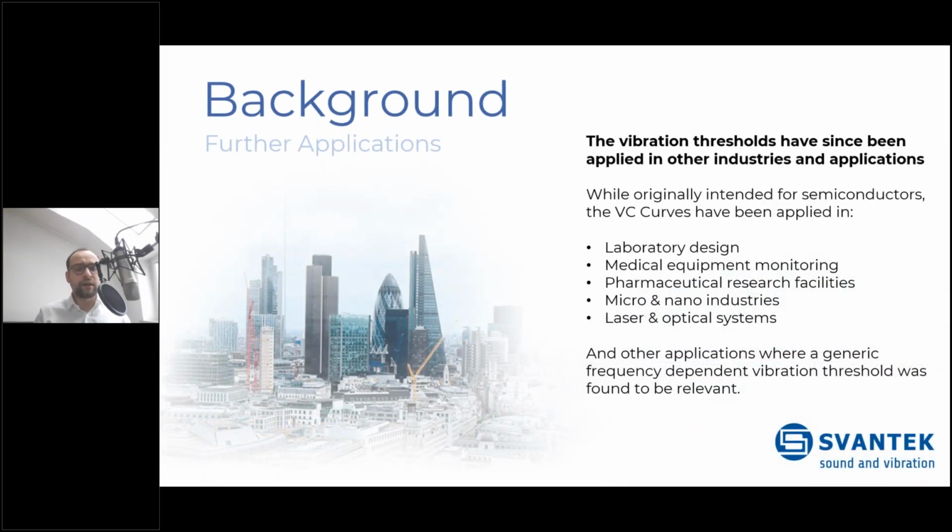And in order to conclude this first background part of this presentation, the vibration thresholds have since been applied in other industries and other applications. As we mentioned in the initial slide, when Colin Gordon did this in the beginning, he defined VC-A to VC-E, and that was it. Since then, even lower vibration levels are required within laser and optical systems, micro and nano industries. The tiniest movement can define the success or failure of a component.